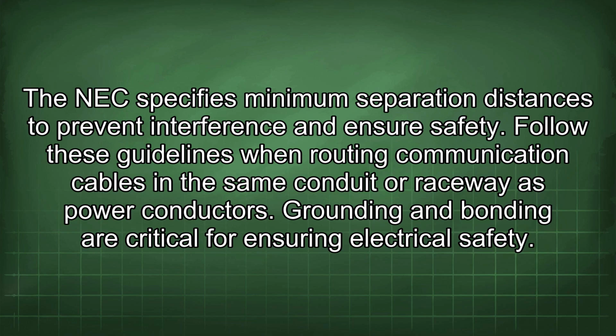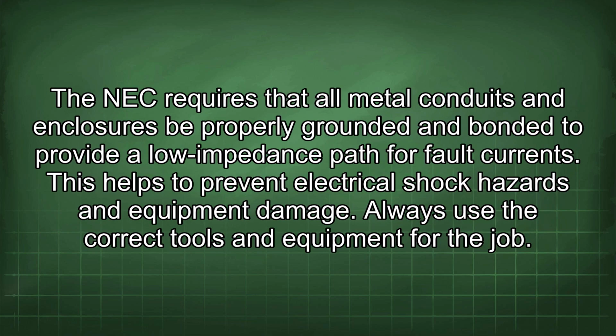Grounding and bonding are critical for ensuring electrical safety. The NEC requires that all metal conduits and enclosures be properly grounded and bonded to provide a low impedance path for fault currents. This helps to prevent electrical shock hazards and equipment damage.